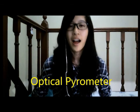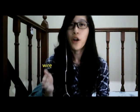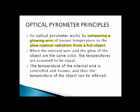Now let's proceed to the other type of radiative pyrometer, the optical pyrometer. An optical pyrometer is useful for measuring very high temperatures, even flames. It works by comparing the glowing wire of known temperature to the glow from a hot object. When the internal wire and the glow of the object are the same color, the temperatures are assumed to be equal. The temperature of the internal wire is controlled and known, and thus the temperature of the object can be inferred.